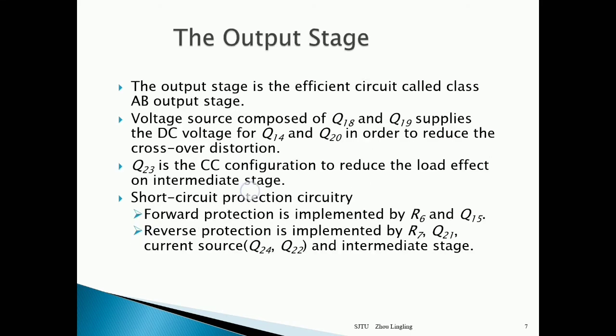The last one is the output stage. First, the level shifting stage. The level shifting stage amplifies the DC signals also. Stage by stage, the DC level increases above ground potential. This high DC level potential may drive the transistor into saturation. The level shifter stage brings the DC level down to ground potential. The buffer is generally an emitter follower with very high input impedance. This prevents the loading of the high gain stage.